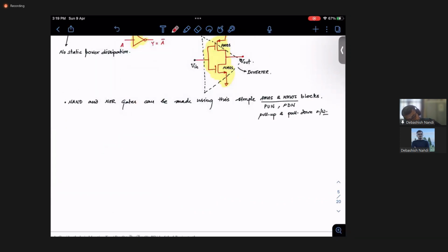So there are two more exclusively unique gates. These are XOR operation. How does the XOR operation look like? The exclusive OR. Basically, the full form is exclusive OR. Okay, the gate symbol looks like this, and we represent it this way. If we expand it, it becomes A B bar plus A bar B. Okay, and how does the truth table look like?